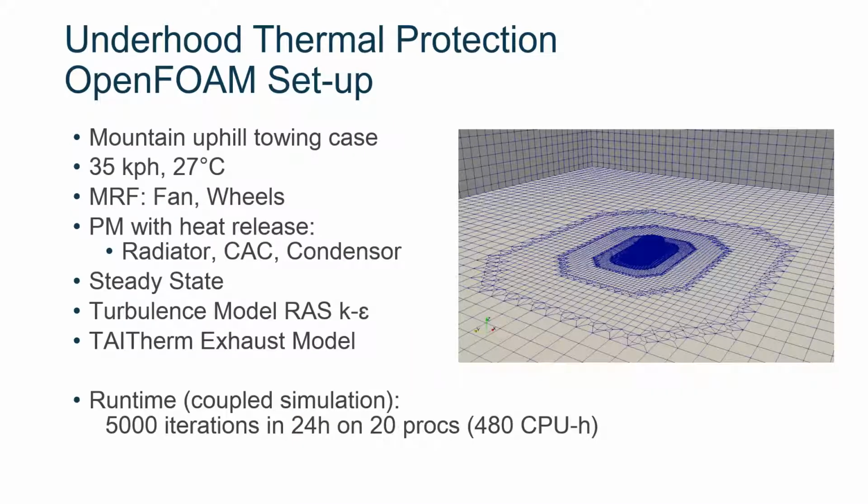So the OpenFOAM setup, we're simulating a mountain uphill towing case, so low vehicle speed of 35 km per hour, MRF on the fan and the wheels. The porous media have a heat release, and it's a steady state simulation with a k-epsilon turbulence model. In TAITherm, we're using the exhaust module. And the runtime for this coupled simulation with multiple couplings was about 24 hours on 20 processors.